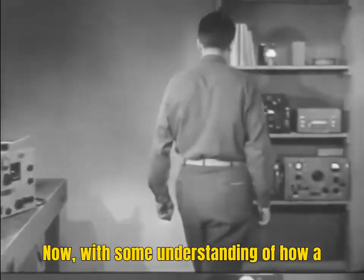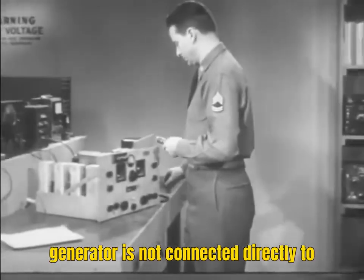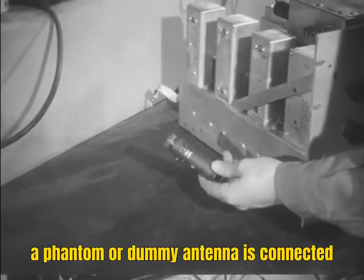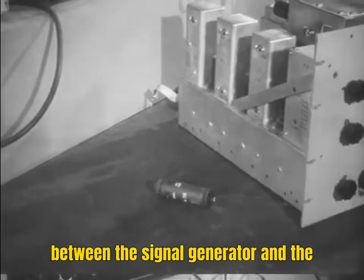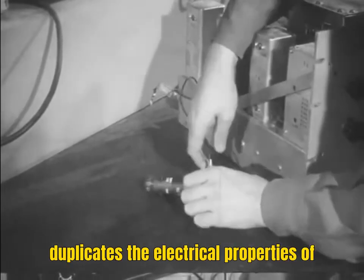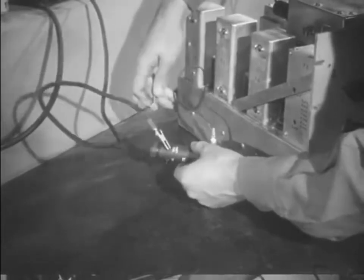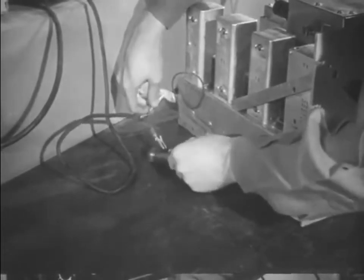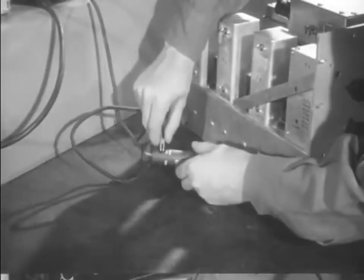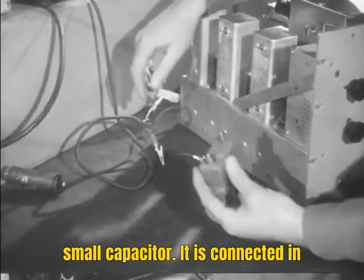Now, with some understanding of how a signal is generated, let us put it to use and test a radio receiver. A signal generator is not connected directly to the equipment to be tested. If a radio receiver is to be tested for sensitivity, a phantom or dummy antenna is connected between the signal generator and the receiver. The phantom antenna simulates a real antenna in that it roughly duplicates the electrical properties of the real antenna. If a phantom antenna is not available, a small capacitor may be used.